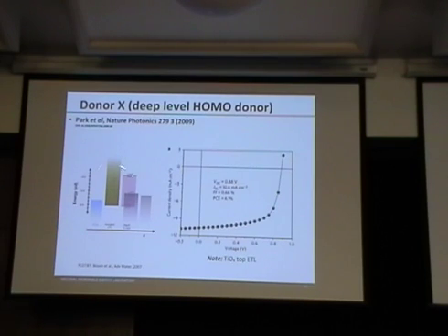And so if we have an oxide that has a nice wide band gap and is p-type, we can arrange for this alignment here, and we can arrange for the blocking up here, because both of the two constituents, donor and acceptor, have access to both of the contacts. So this is the kind of scenario that we said we wanted. And the claim was that nickel oxide should give us that.